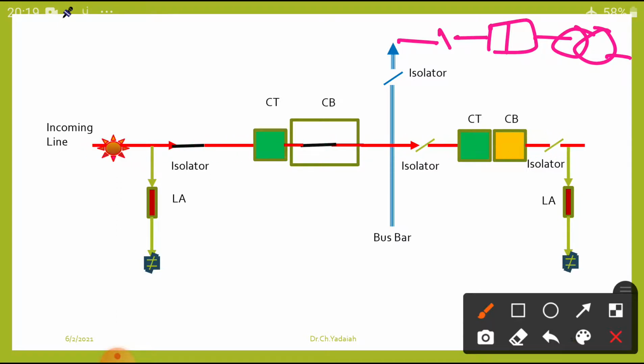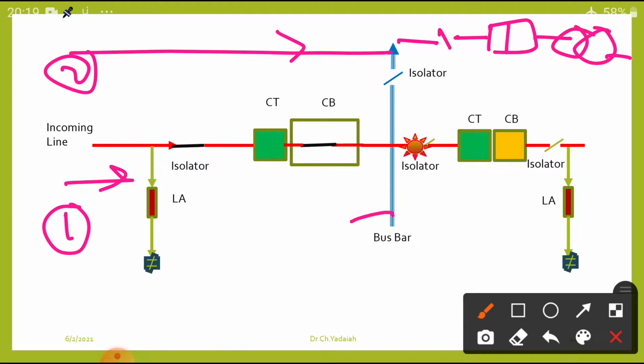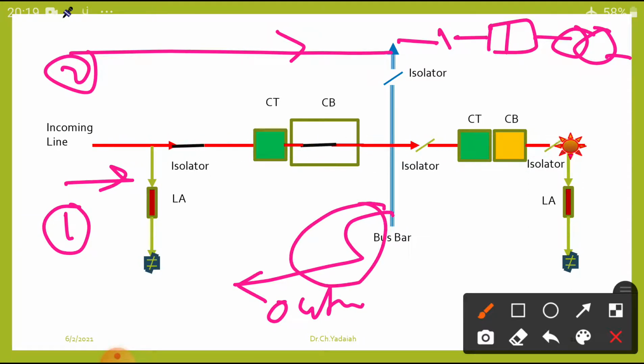Whether it is going to a single feeder or I am going to connect another feeder also, one comes from one place, another from a different place, or sometimes from the bus bars themselves it goes outside as outgoing feeders to different places. Before that I am going to use the same arrangements. All these arrangements, isolators, CT, CB, everything will be present in the system.